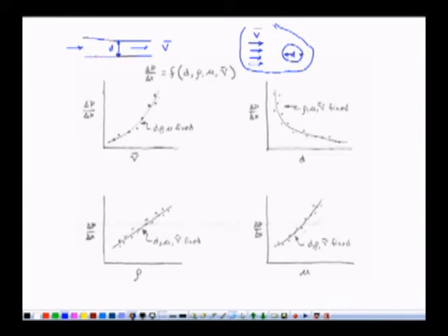d. We want to know what is the pressure loss between these 2 points. What is the pressure at this point? Let us say P1. What is the pressure at this point? P2, and this P2 is always less than P1 because viscous effects play an important role. If we have a real fluid flowing through this pipe, then P2 is less than P1 because some of the pressure is lost to overcome the frictional resistance offered by layers and at the solid boundary, right. So, this P2 is less than P1.